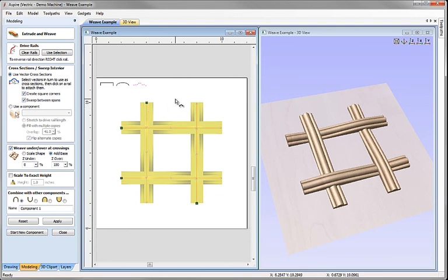So by reversing just the first drive rail, then that's going to change the order because the software looks along the first drive rail in order to find the first crossover point here to decide how it's then going to go ahead and orient and weave all the other areas that the lines are overlapping.